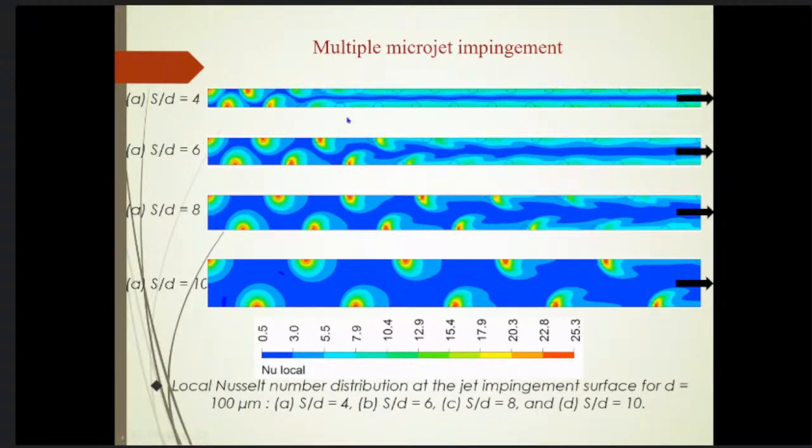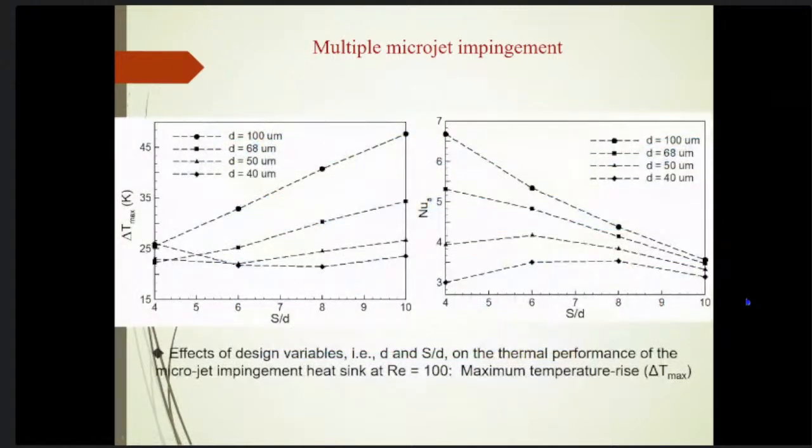These are again the flow structures in the same line, when the jet is striking on the surface. We see what combination and what diameter of the jet can give us the best possible results in terms of minimizing the temperature and maximizing the rate of heat transfer, especially the heat transfer coefficient and Nusselt number, and minimizing the flow resistance, the pressure drop, and the pumping power required.